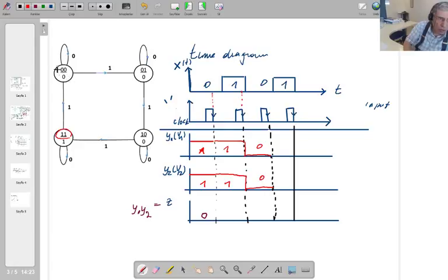Now in 0, 0 state, you are applying 0, and it says here no change, because if your present state is 0 and you apply 0, you come back to 0. So your next state is 0, 0. Your present state is 0 now, and you're going to apply 1.